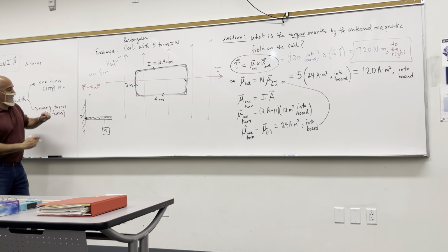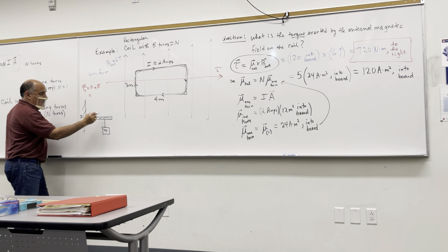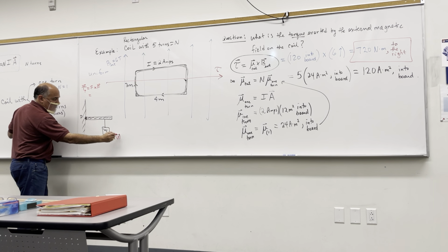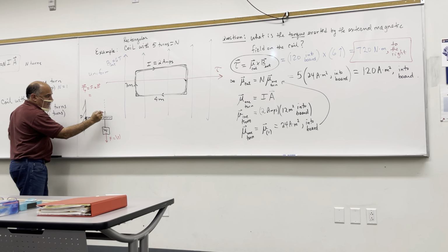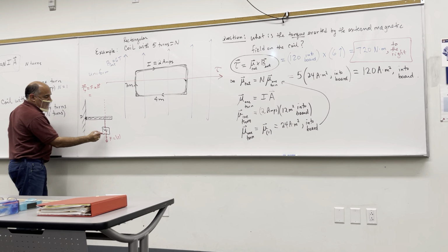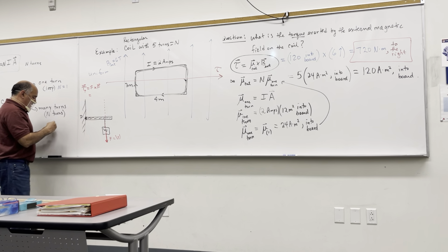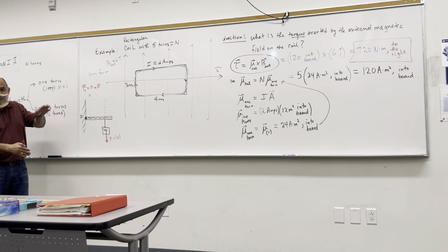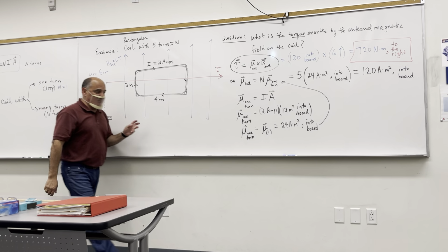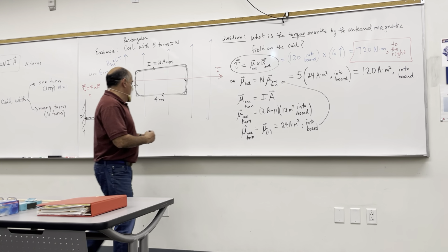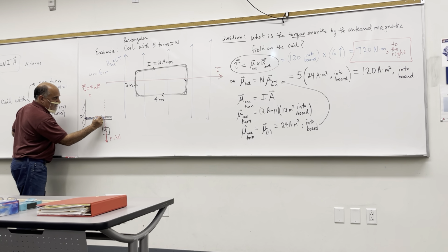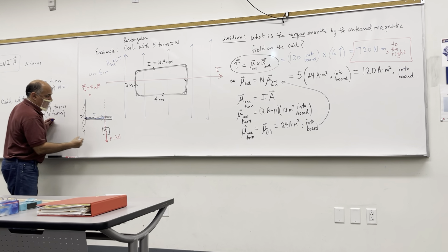R is starting at the point that you take torques about. The force has a magnitude of W, and it's down, right? The line of action of that force is like this. And so R has to be a vector that begins at point P, and the end of vector R has to be anywhere on the line of action of that force W or F. Well, the simplest thing to choose is this. So R is to the right, and the force is down.